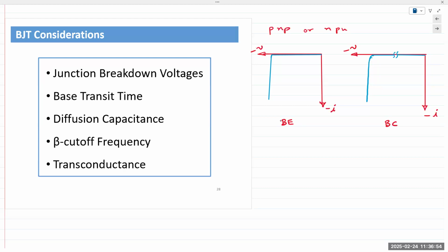So now that you know the answer, think about this for a few seconds and think why that might be the case. Both junctions are reverse bias. The base emitter is also reverse bias. Collector base is also reverse bias. We're not looking at device function in any way. Right now, we are simply looking at the PN junctions. But why are the two PN junctions, even though both of them are reverse bias, why do they have slightly different values?